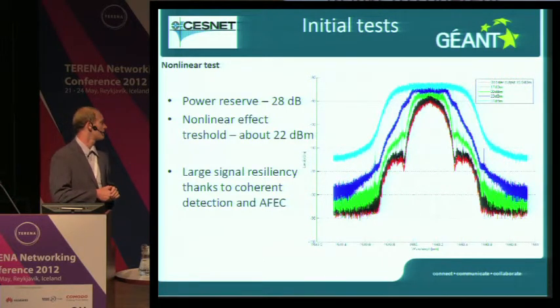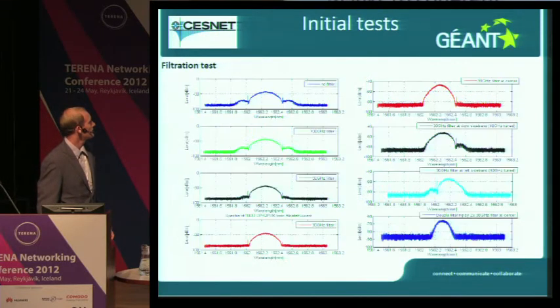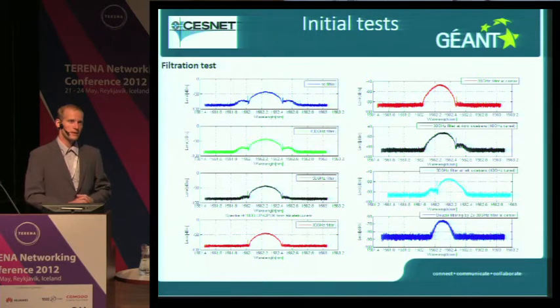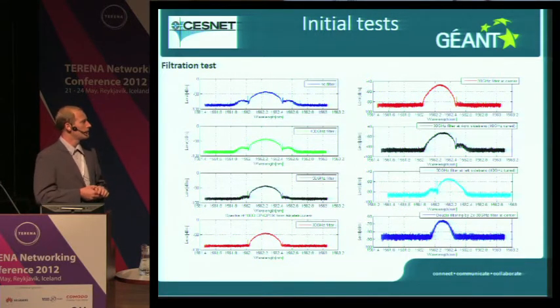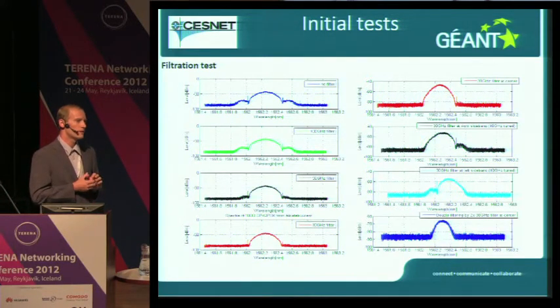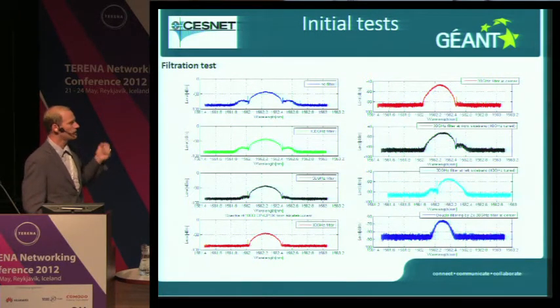Another simple test which we made is a filtration test, because as your network grows bigger and bigger, you may find more filters in line in one end-to-end connection, cascaded. So we tried to filter the signal and see how much filtering it can bear before the connection is lost.